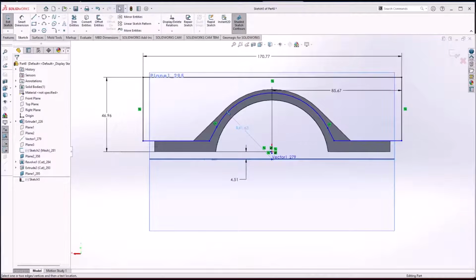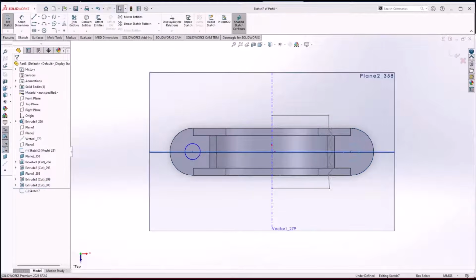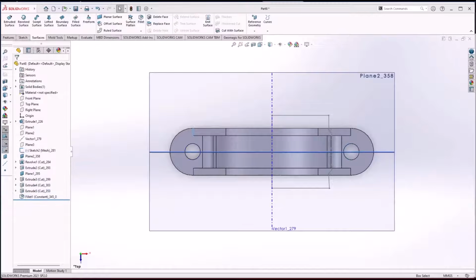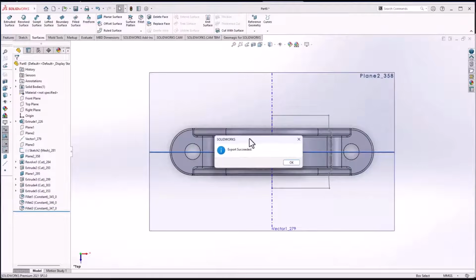If you are not understanding why you would want to do that, there are instances where maybe you have a CAD model and you scan one and you align the scan to the same coordinate system that the CAD model is. And we can load the CAD model in, by the way, from SOLIDWORKS back into Design X to use as a reference to align the scan data to it, and then align it together. And then if you make modeling changes and send those over to SOLIDWORKS, they'll come in the same coordinate system. So there we go.